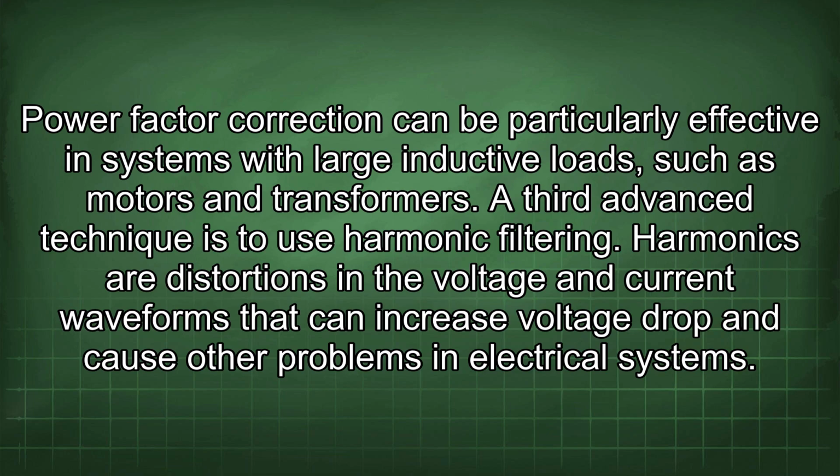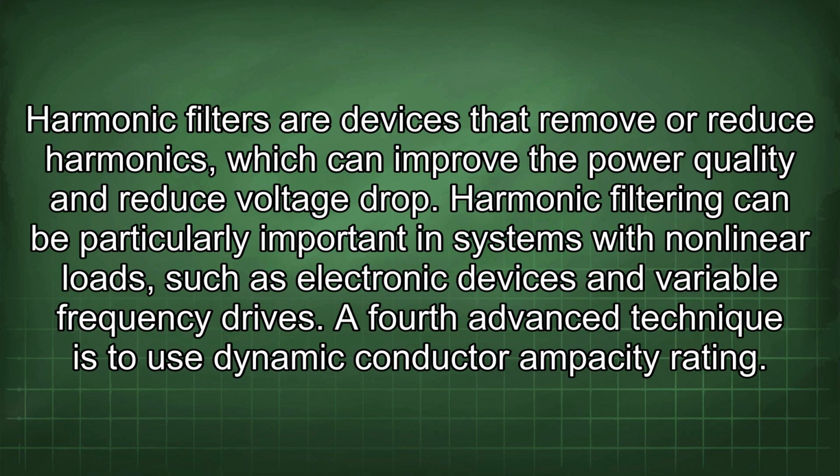A third advanced technique is to use harmonic filtering. Harmonics are distortions in the voltage and current waveforms that can increase voltage drop and cause other problems in electrical systems. Harmonic filters are devices that remove or reduce harmonics, which can improve the power quality and reduce voltage drop.